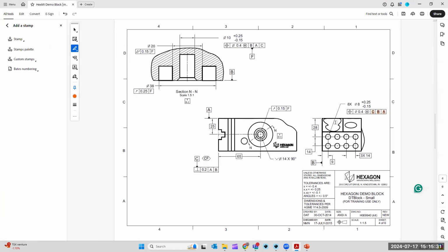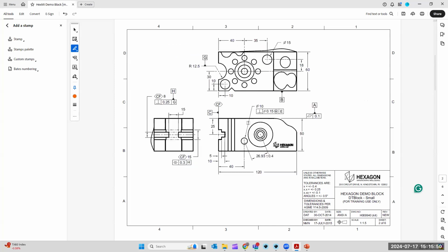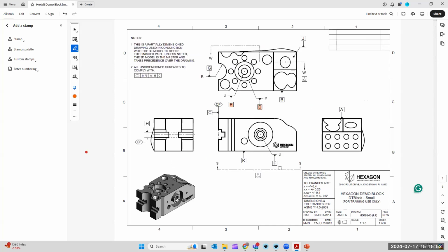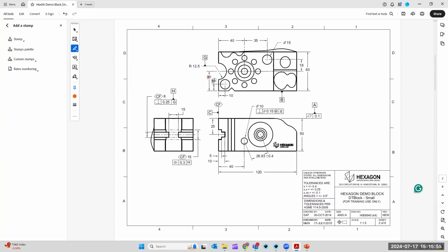This one here would have to be a CBA alignment, and this one here would have to be a BAC alignment. So now we're going to apply everything we've learned to be able to physically compare the real part that's on a machine, or at least program it ready to do the comparison. So we want to know, is that real part that's been manufactured compliant to this engineering drawing and all of these tolerances that are on this drawing? Now, obviously, that's the intention of a CMM machine. Other than reverse engineering, it's to verify that a part is compliant to engineering specs. Make sense?